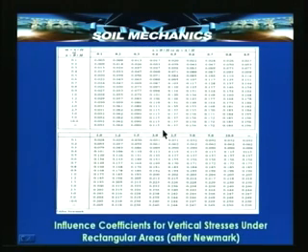The table also gives the influence coefficients for different non-dimensional ratios m and n, which have been defined even earlier. In this chart you can see that m is half the longitudinal dimension non-dimensionalized with respect to the depth, and n is half the cross-sectional dimension non-dimensionalized with respect to the depth, for a whole range of m and n from 0.1 to infinity.